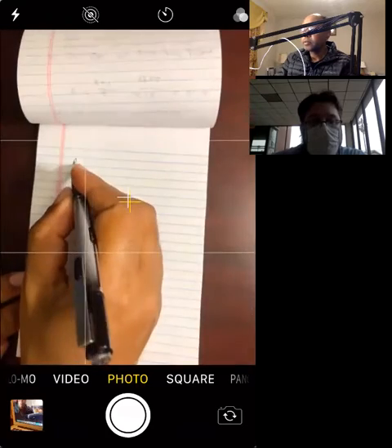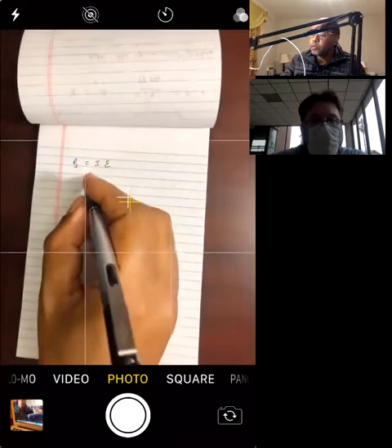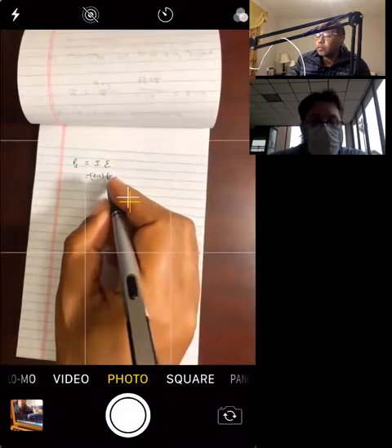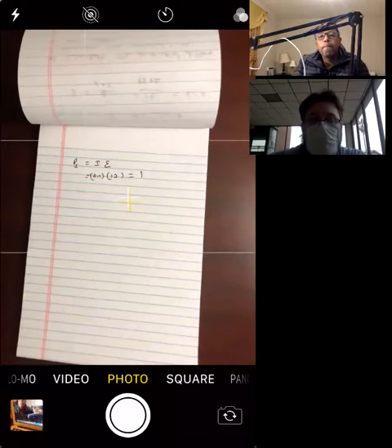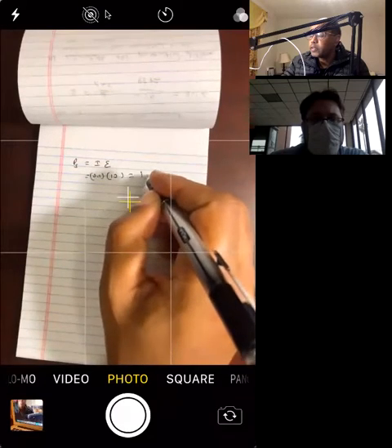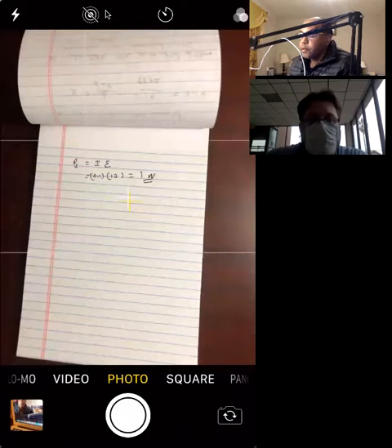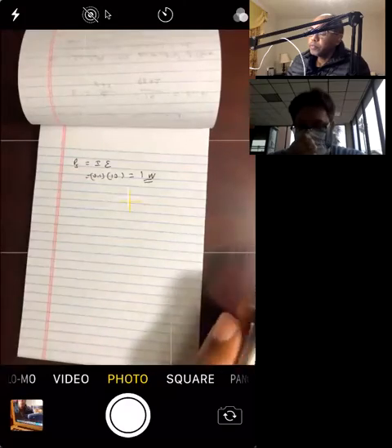And that is simply current times EMF, all right? So the current is 0.1, okay? And the EMF is 10, all right? So that is 1. What's the unit of power? Watt. Watts, okay? So this is the rate at which non-electrical energy is being converted to electrical energy, all right?